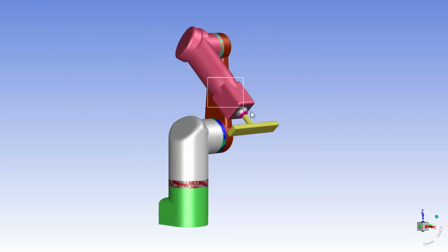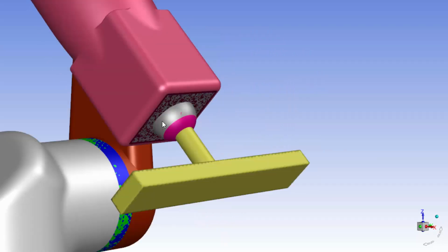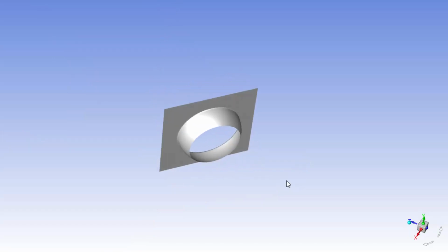Because the meshes of the last arm segment and the end effector intersect rather than overlap, I've used an auxiliary connecting mesh called a collar mesh that overlaps the spherical wrist of the end effector and the front wall of the arm segment. Here's what it looks like.